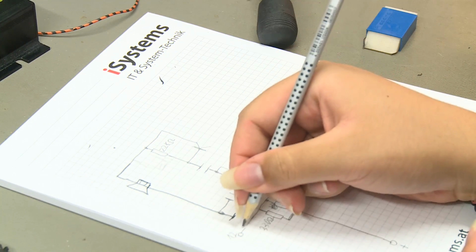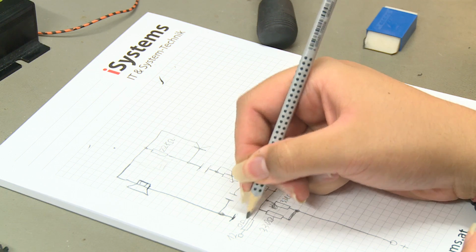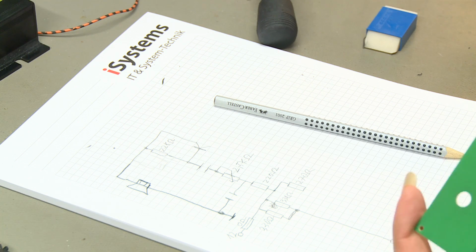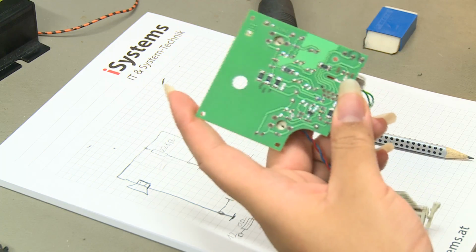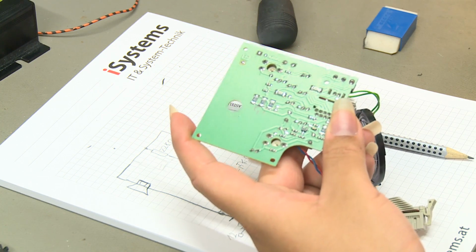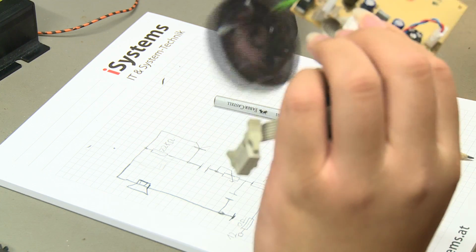So here we have a 0 ohm jumper. It's just used to cross another trace in the PCB because it's a single layer PCB and they don't have any other way to cross traces. Which in fact is pretty amazing, that this whole PCB has only one jumper resistor. They managed to make it entirely on a single-sided PCB.